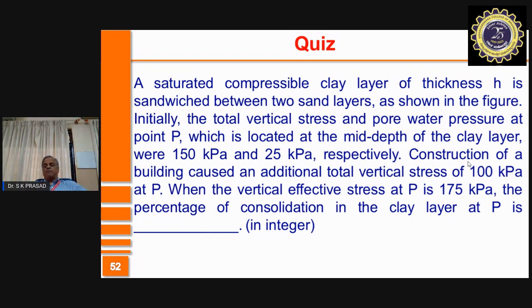So in a span of 20 meters in the ring foundation, the differential settlement is of the order of 1.6 meters, which means the tower is tilted by almost 4 to 5 degrees. And you have a problem of differential settlement which needs to be addressed.